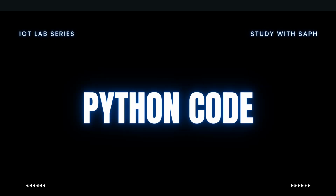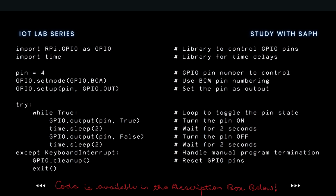Next, we have the basic Python code for this particular experiment. As we can see, the first few lines having the import statements are the libraries required for the rest of the commands which we use in the program. We are importing RPi.GPIO with the alias name GPIO, so anywhere GPIO is used, it's taken from this library. The time library is used for all the delay statements, such as time.sleep.